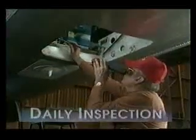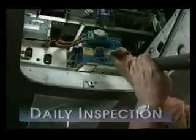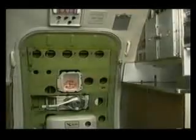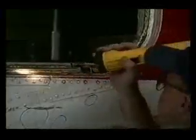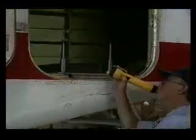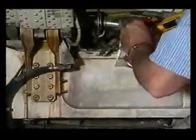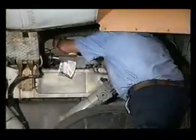Areas which the baseline inspections have proven to experience no corrosion should not appear on the map, and therefore will not be the subject of daily inspections. If moderate or severe corrosion was discovered during the baseline inspection, there's a corrosion problem. These areas should be inspected carefully during daily inspections of all fleet aircraft of that type, and the problem should be addressed. If the component is accessible during each daily inspection, the mechanic should visually inspect the area for corrosion or factors which may cause corrosion.